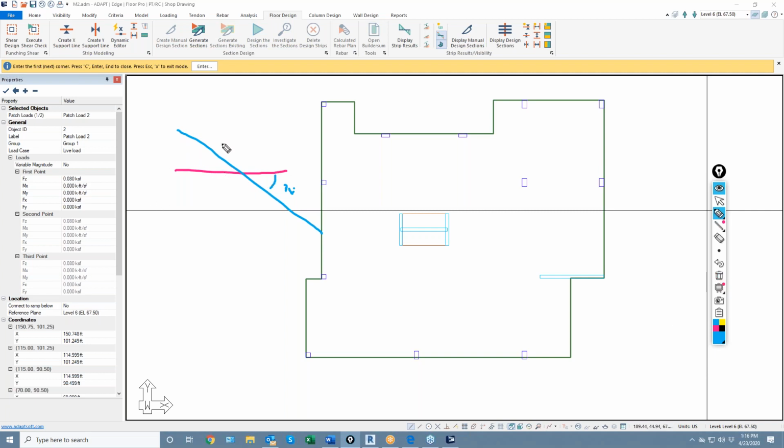So what happens is you might have another cut. I'll draw this in yellow. You might have a cut belonging to an X direction support line here for this yellow cut, and that banded cable really is going to affect the results essentially in both directions, where its really primary purpose is maybe to affect the results for strips in just one direction.